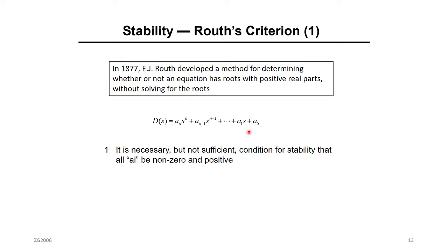So our job when we design the controller for stability is to make sure the real part of the root of the characteristic equation is negative, or zero at least. All right. Now, we always start from the characteristic equation and we solve for the root.